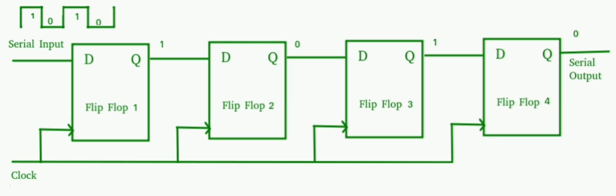Comparison of various logic families, very important. Logic parameters: RTL, basic gate NOR, fan out 5, power dissipation 12 milliwatts, TPD 50 nanoseconds, figure of merit 500, noise margin 0.2 volts. DTL: basic gate NAND, fan out 8, power dissipation 8 to 12 milliwatts, TPD 30 nanoseconds, figure of merit 240 picojoules, noise margin 0.75 volts.